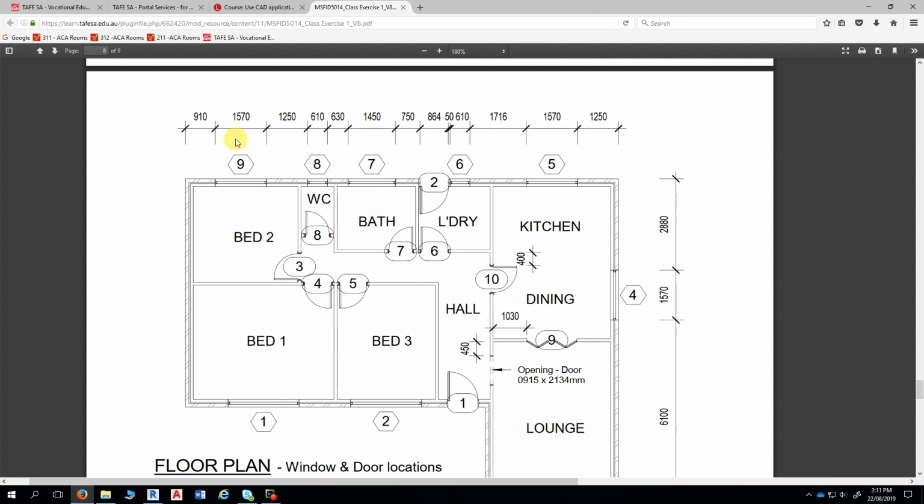So once you've loaded your families in, you then create your custom types, place them in the walls, and then create your dimension set as you did with your intersecting walls. When you select each of the doors or windows, it'll activate a couple of dimensions, and you can use those dimensions to position your door or window.